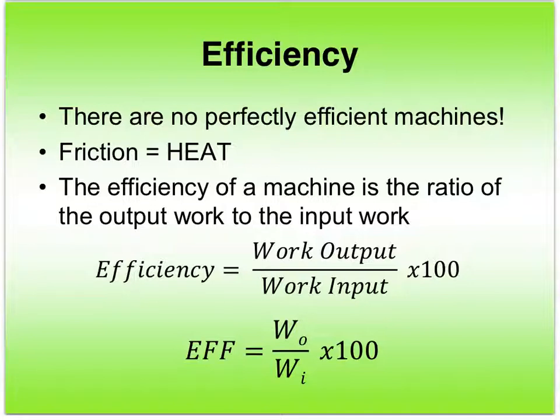If you look at an automotive vehicle, your normal car is only about 23 to 25% efficient, which means, let's say it's 25%, if you're paying $4 a gallon for gasoline, only one of those dollars is actually causing your motion. The other $3 is causing heat and friction, and it's lost to heating up your engine and the environment around you. So you're really paying quite a bit just to heat up the air and heat up your car instead of actually moving you.